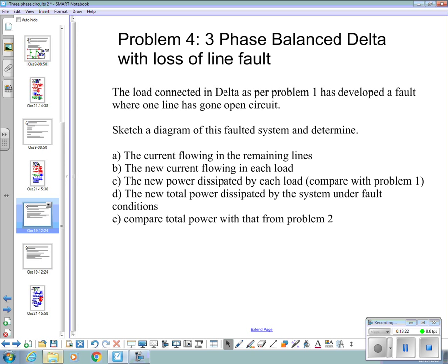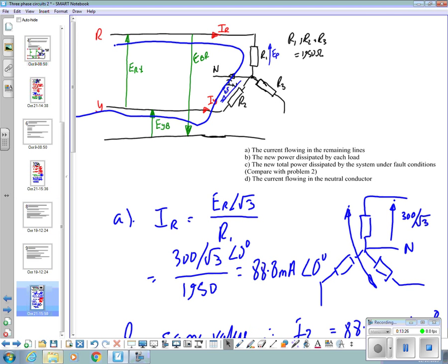I've got a quick question about that last question. We all dropped the same phase. Yeah. If we dropped one of the other phases rather than the blue, would we still get the same answer? You'll still get the same magnitude, 60. The angle will be different. So we still get 88. Okay. Yeah. I believe. Might not be 60 degrees.